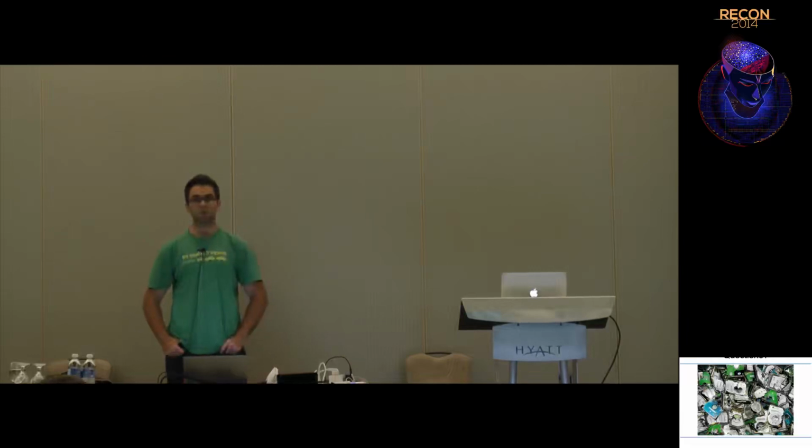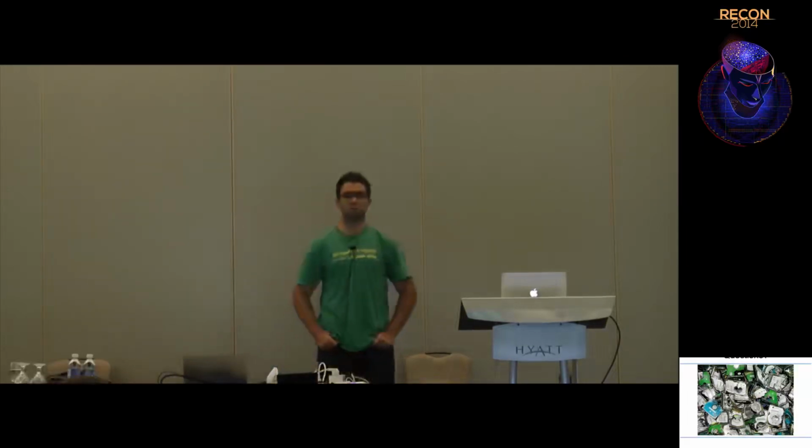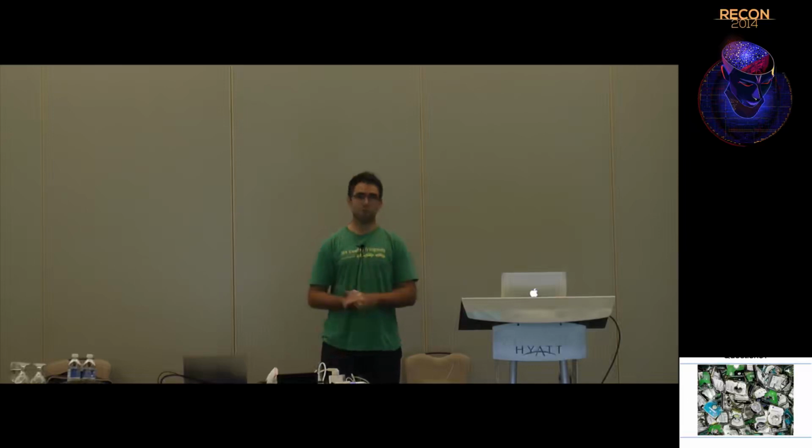Is there any collection of firmware images on the internet that you could download a whole bunch of and try to do a comparison to figure out how varied in functionality and possibly hardware they are across the same vendor? So first, there are several firmwares available for the same drive model depending on where you get it from, like Dell or Seagate directly. You can do comparisons between those firmwares, and I tried to compare a bit also for different revisions. Like for this drive, you have one revision, and they just fixed one small bug that was causing the drive to break, and brought out a new revision. And I looked a bit to find the diff between the two.